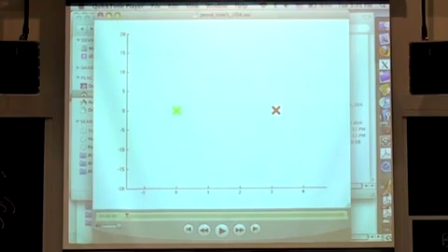Now all I told you so far is I know how to take an LQR problem and try to estimate the basin of attraction. So that's step one: take a linearization around my goal state, design an LQR controller, and estimate its basin of attraction. And that looks like this. We've seen cost to go functions for the ellipsoids.